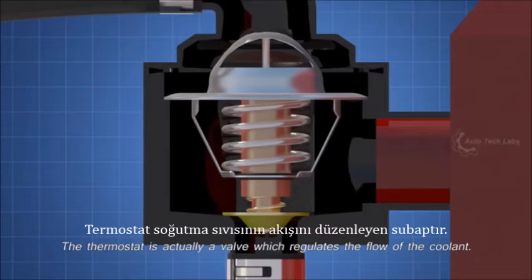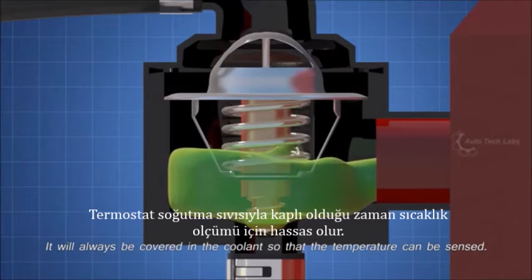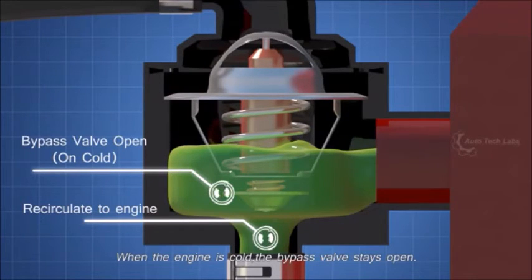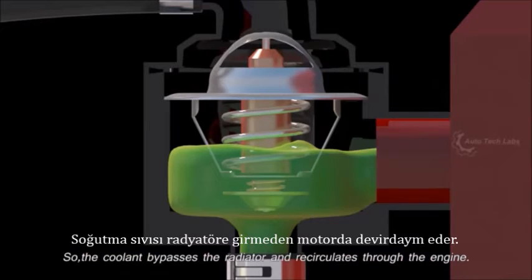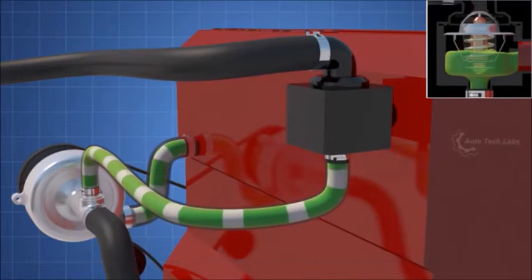The thermostat is actually a valve, which regulates the flow of the coolant. It will always be covered in the coolant, so that the temperature can be sensed. Let's start the operation from a cold engine. When the engine is cold, the bypass valve stays open. So, the coolant bypasses the radiator and recirculates through the engine. This helps the engine to heat up to operating temperature quickly.